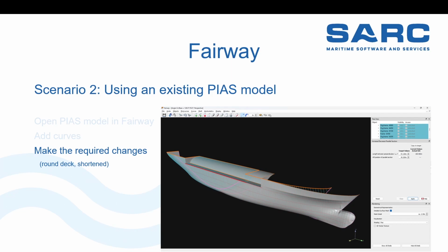Then I wasn't done. There was a parallel midship, which I cut out there. That's a separate option. It's not scaling. It's really throwing away everything from a certain length to another certain length. So if you don't have a parallel midship to start with, you end up with something ugly, because it will not match fore and aft ship. So beware of that. You can throw away any piece of the vessel there, but it would help if that would lead to something sensible, of course.